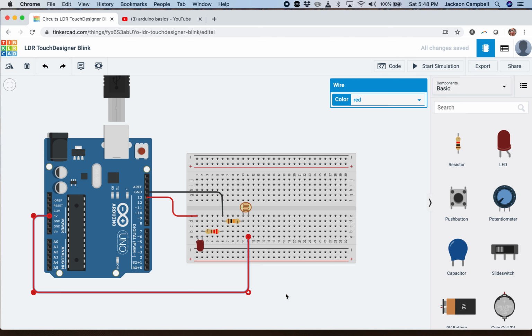All right? So what's going to happen is the electricity is going to go through the resistor, and then on this side we're going to measure, we have a path to ground that goes through a 10K resistor. Now if there's anything less than 10K, it's going to want to send electricity through that less resistant path. If the resistance goes above 10K, then it's going to go through the escape route through this pull-up resistor line back down to ground.